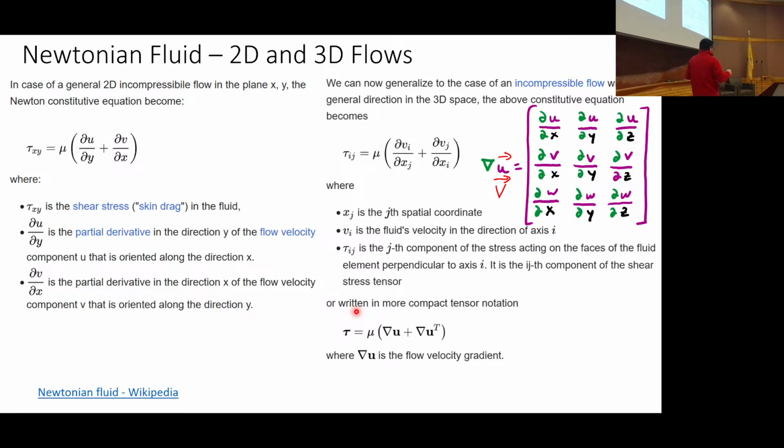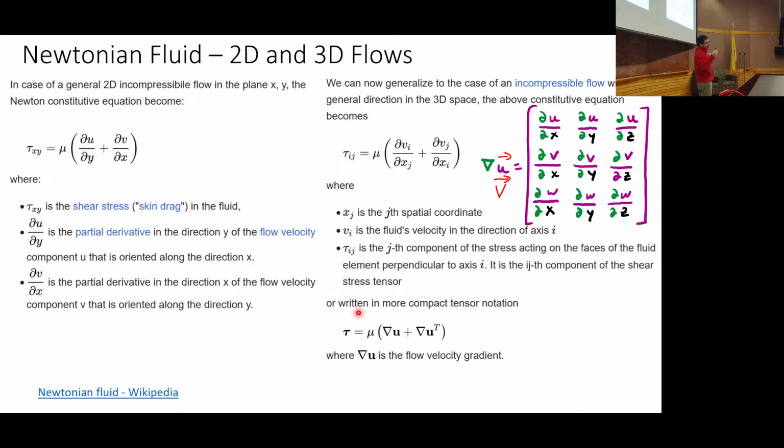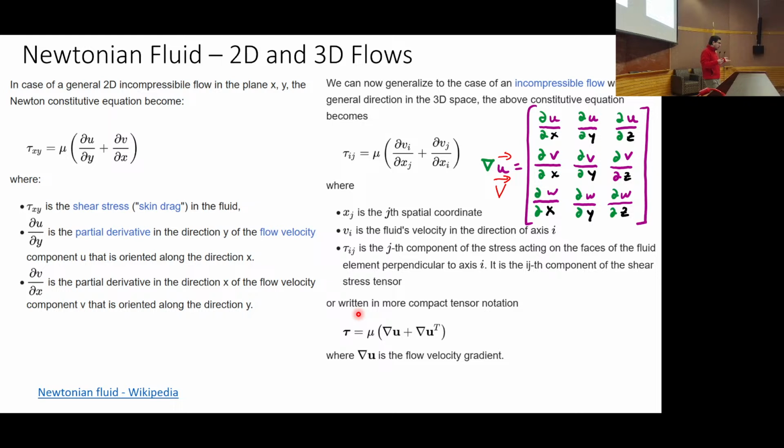When you do simulations, you can have it calculate shear stresses, you can have it calculate normal stresses. Normal stresses are going to be in the form of your hydrostatic pressures. Okay. But you can have it calculate shear stresses. But often we care more about flows, and we do care about the integration of these shear stresses or normal stresses on surfaces so that we can calculate drag.